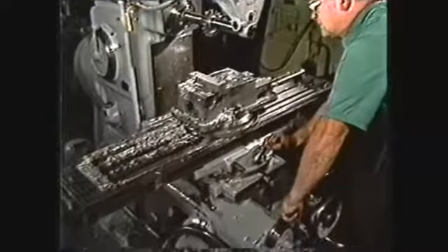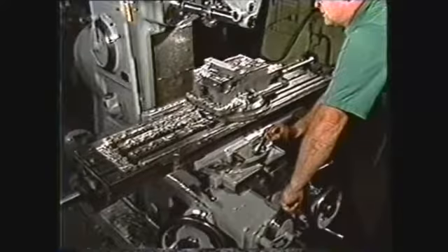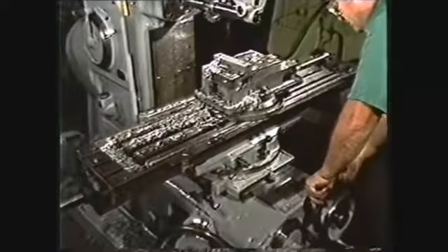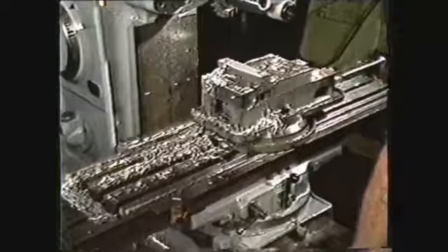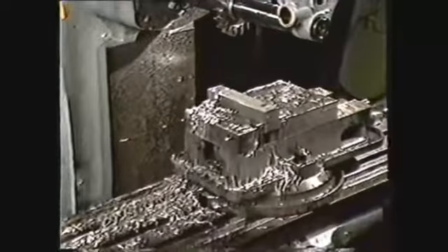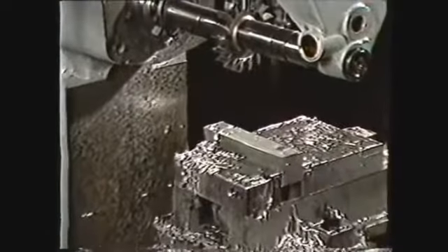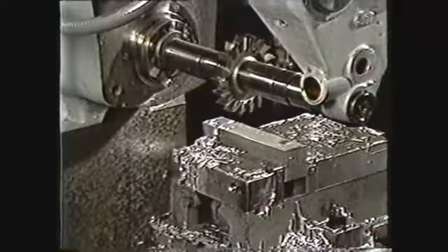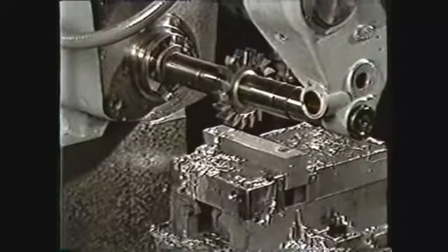Position the workpiece on the table so that the side milling cutter can be placed on the arbor to give clearance for the arbor support over the vise holding the work. Using the cross feed and longitudinal feed on the table, move the work into position for the cutter to make the desired cut.